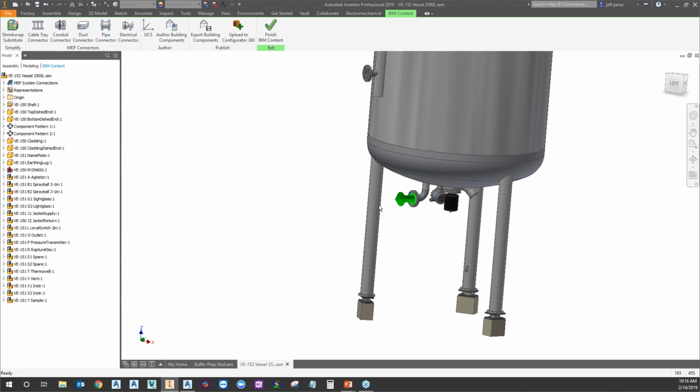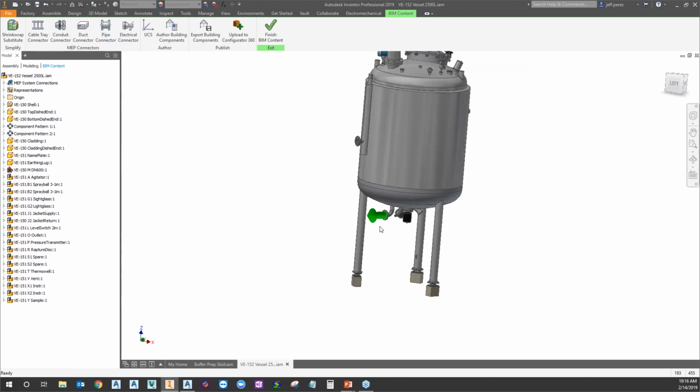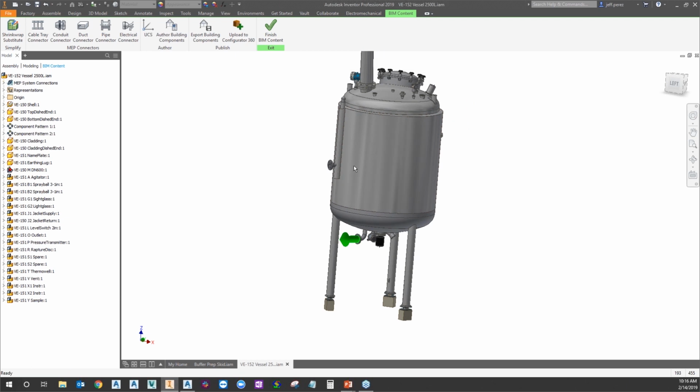Okay. So now this is telling me that I did author this nozzle in Inventor. You could do this same technique for all nozzles that you have in your assemblies or part files, or even if you're receiving SAT files, STEP files, anything that you're getting, you could do this type of method. If I wanted to, I could do this vent type nozzle that I have right here, but I'm going to show you how to do that in Plant. So I'll leave this one alone for right now.